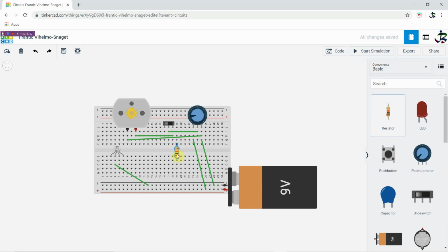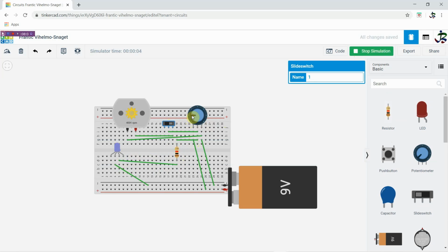So I have connected the resistor. Now the middle terminal is connected to the resistor and the resistor to one of the LEDs. I used the blue. So right now it is blue, as I switch on the light. Now the intensity of the blue is changing. It's very low. So like this, the voltage is decreasing very low, because at this terminal the voltage is very low.